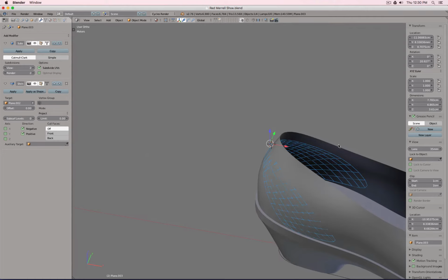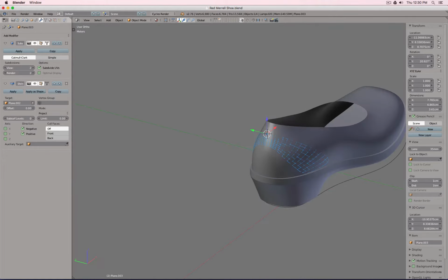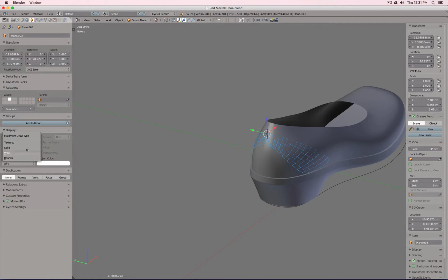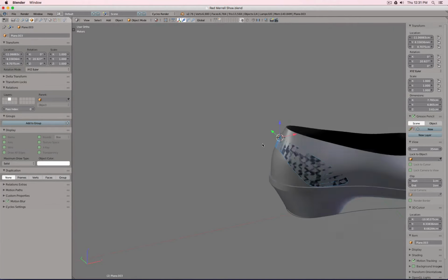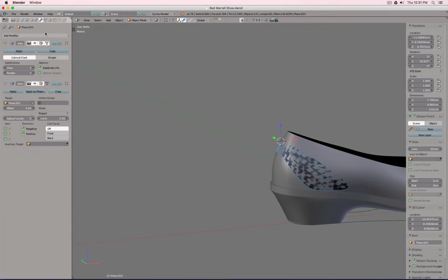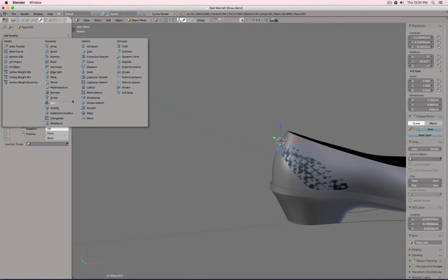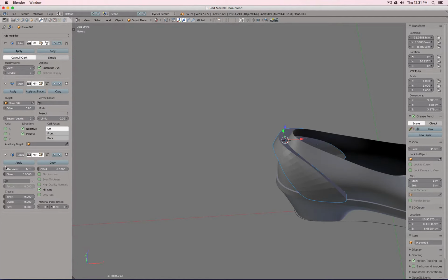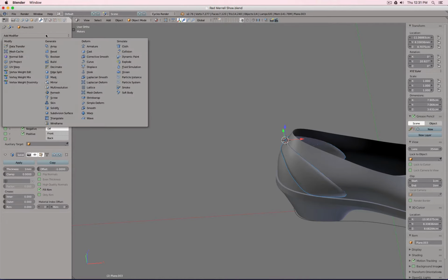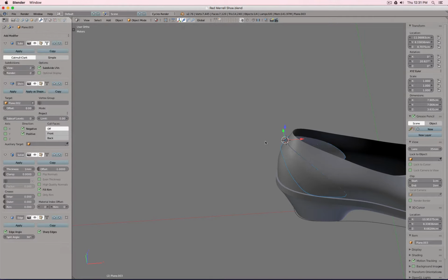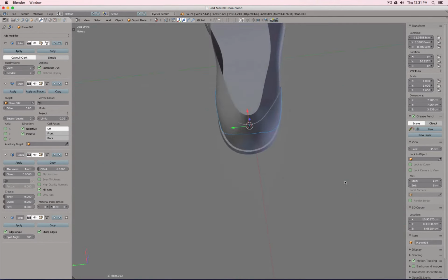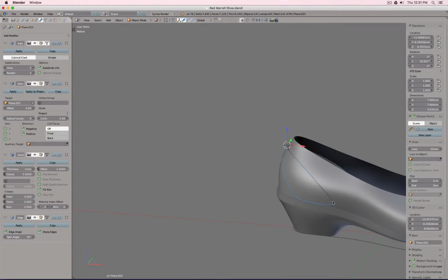So in case our fabric piece here in blue penetrates the shoe surface, it actually will rest on top of it. So we can turn this one back into solid. Now we don't really see it. So let's give it a solidify thickness, 1 centimeter is too big, a millimeter maybe, so we can see it. Shade smooth. Let's add an edge split to crispen up the edges. Ta-da! And then we have this stuff down here.